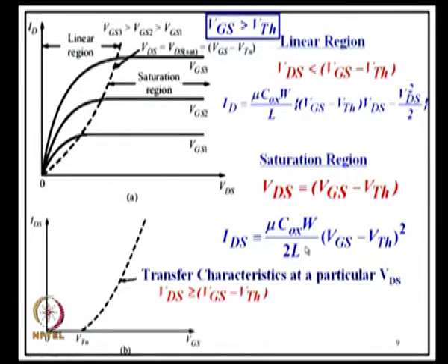So, the way you do it is, you will see that you have seen it already, that you increase the C oxide and maybe you can reduce W. Increase the C oxide and reduce the channel length, all these give rise to better drain current and better transconductance, that is delta IDS by delta VGS, which is proportional to this quantity.